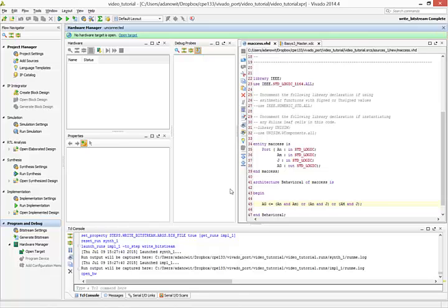Plug the FPGA into your computer through USB, turn the board on, and give Windows a few minutes to install the driver base necessary for this board. Once all that's done, you can come back to Vivado, and now you'll see we have this title Hardware Manager up here, and this green context bar that says No Target is Open, and a link to Open Target. Click on Open Target, select Auto Connect.